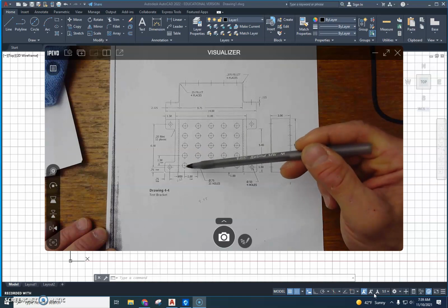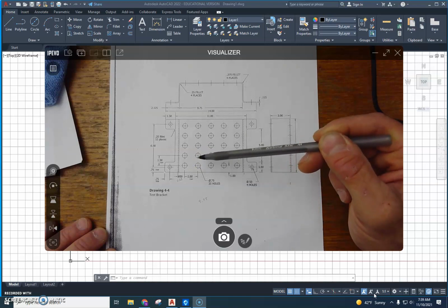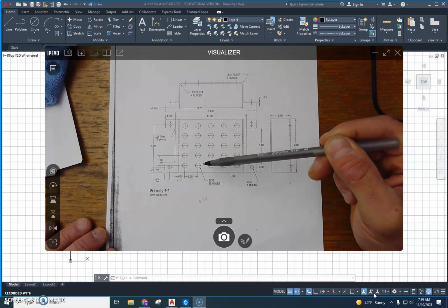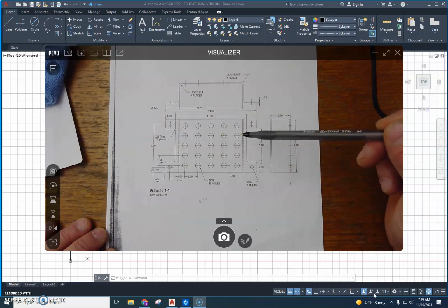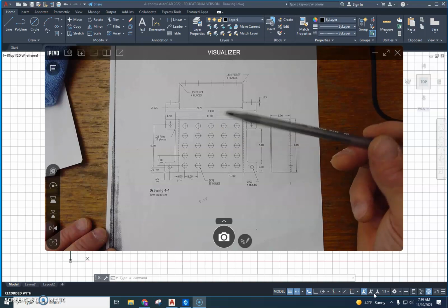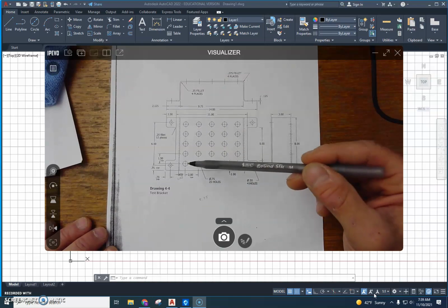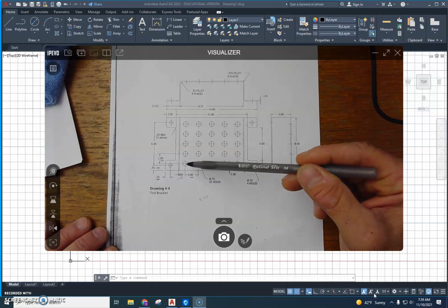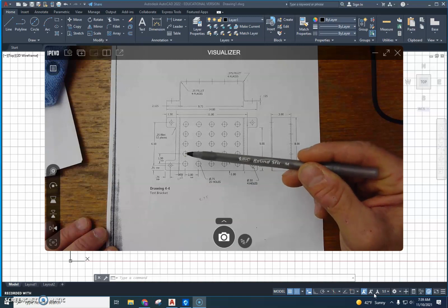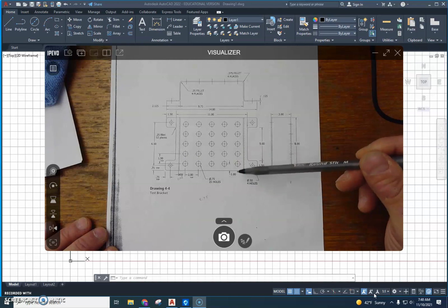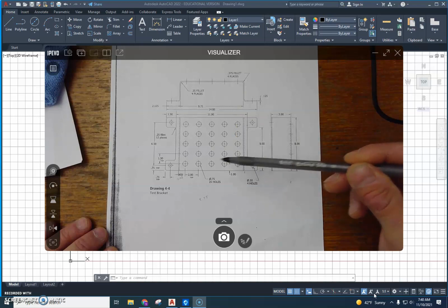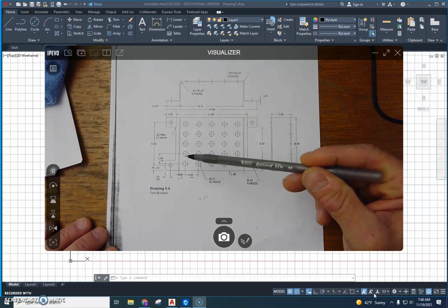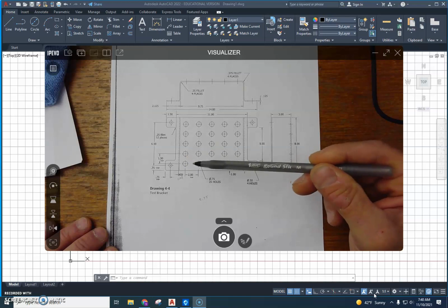And you can see the circles here are 2 inches apart going left to right, and 1 inch apart going up and down. There are 5 columns and 5 rows. Now the hardest part is figuring out where this gets centered. You know they're 1.5 apart here. I said 1, but they're 1.5. They're actually 1 inch off the bottom and 1 inch off the top, and then they're 1.5 inches apart. This way they're 2 inches apart.